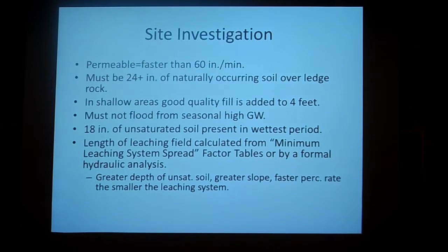You need to also make sure that the seasonal high groundwater level would not flood this area, and that there's 18 inches of unsaturated soil present even in the wettest period. Then you can calculate the length of the leaching field from the minimum leaching system spread factor tables or by a formal hydraulic analysis. The greater the depth of unsaturated soil and the greater the slope of the land with a faster percolation rate, meaning you could design a smaller leaching system.